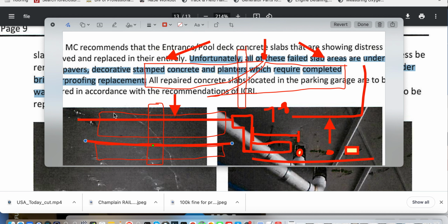If you were to take an elevation measurement from the top of the concrete slab, not the tile, but the slab, and then go underneath and take a measurement, you would see a deviation of the thickness. Or if you drill the core hole all the way through, and they did that, and then you send down a little camera at 11 inches and look at the walls, you would say, oh, I see it's delaminating.